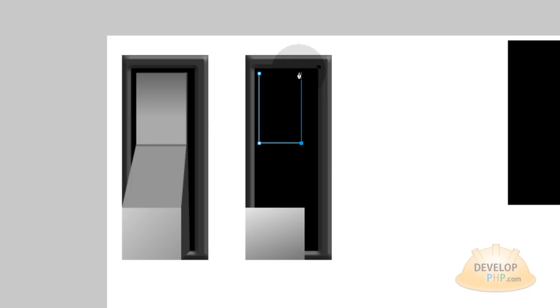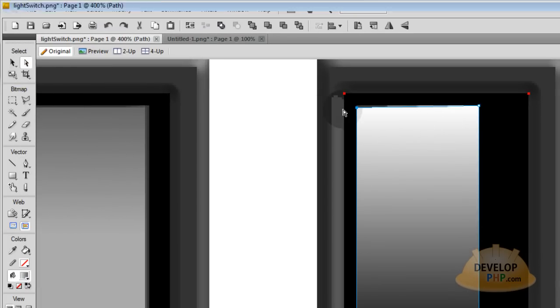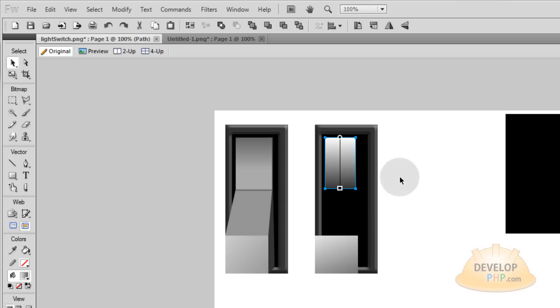Then you go back up and you go right there. And you see how mine's jagged? If you zoom in, you'll see I'm jagged there, so I can just move that point. Grab my sub selection tool, grab that point, move it up. And then everything's perfectly straight on the shape. Now it looks like this one has to be a little wider to match the width of that other one. So let's make it a little wider. Just highlighted those 2 points by holding shift.